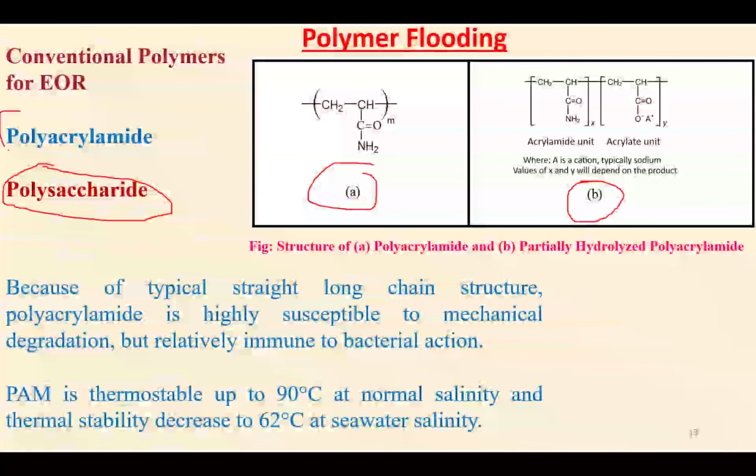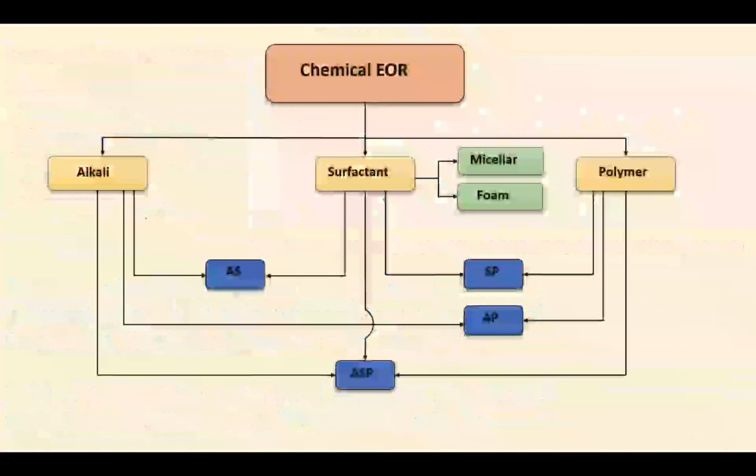Now, polyacrylamide and polysaccharide have some properties. Polyacrylamide is basically resistant to biodegradation, but it is susceptible to mechanical degradation, and the reverse is true for polysaccharide. Now, if we go for the surfactant, again a very commonly used chemical, and most importantly,